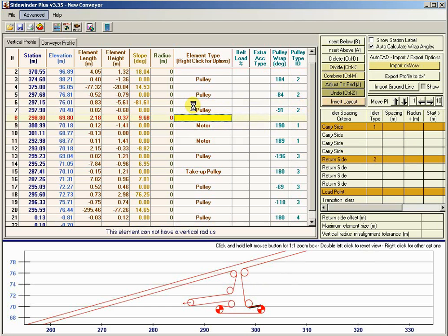So there's a distinct advantage of actually entering all the wrap angles in your geometry correctly, because when it goes to calculate the pulley and shaft forces and tension vectors on the shaft, it'll calculate all those correctly, and obviously add the pulley weight, which is always going to be a downward force. So it's essentially just very nice to do that.